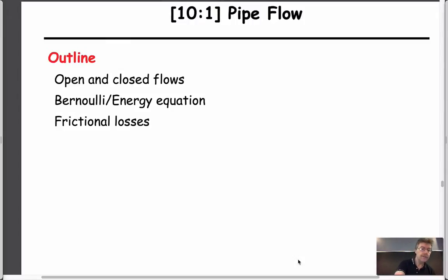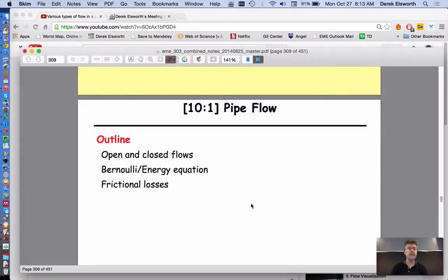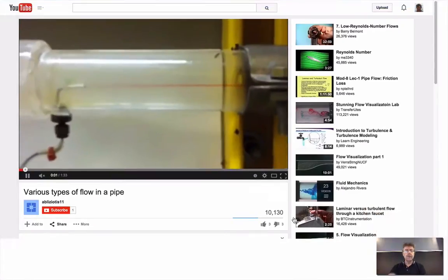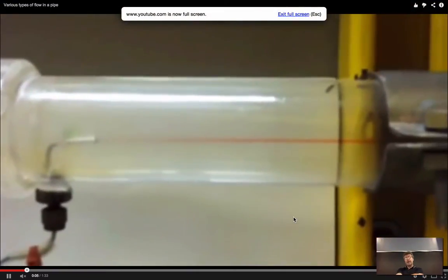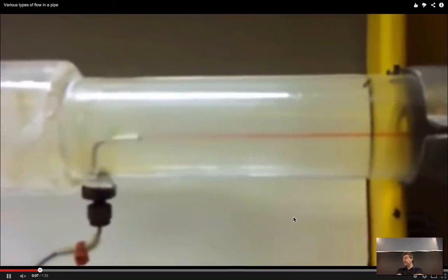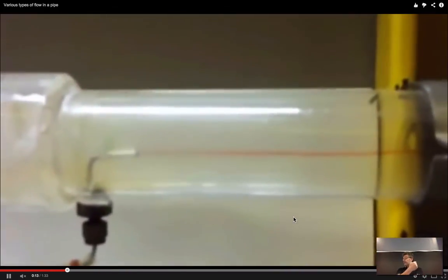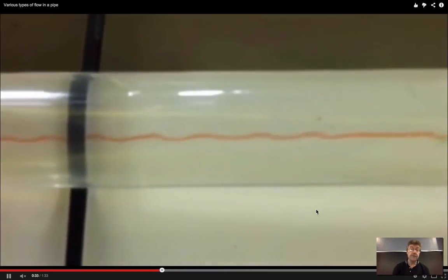So we made the point already that when we look at, let me go back to this. When we look at the behavior of a fluid, if we want to be able to represent the behavior, we're going to have to look at three different requirements. That the model is correct, geometric similitude, that it's running at the right velocity. And so, in other words, we'd expect that we have to compute things at the right Reynolds number. And finally, that then if we do that, we can calculate what the forces are on the structure through something like an Euler number.